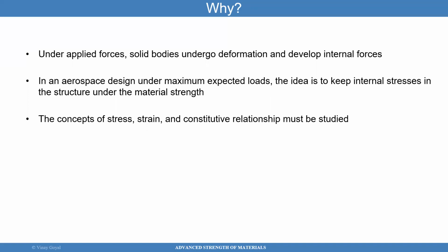If it's an aerospace design, such as an aircraft, say you want to design a new aircraft that's unique, that's special. Well, you want to know what thickness fuselage you need so that when it goes under pressurization and under bending loads and torsional loads that it's going to experience during flight, under those maximum expected loads, the stresses in the skin of the aircraft can survive the loading environments. And we use the material strength to determine whether a structure could fail. So the stress is below the strength, that's a good thing.